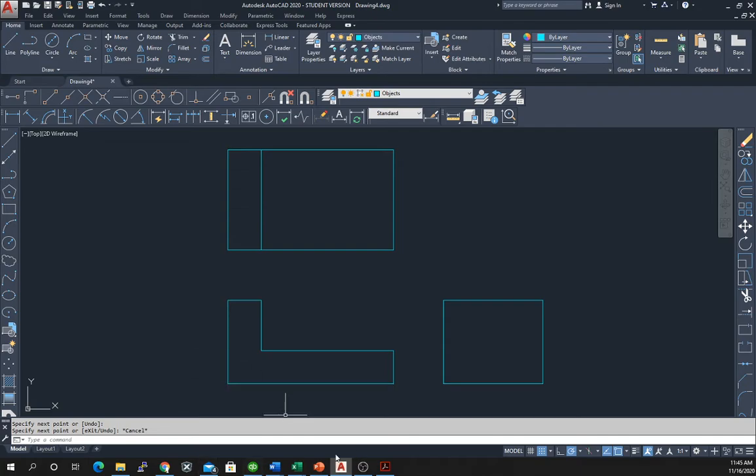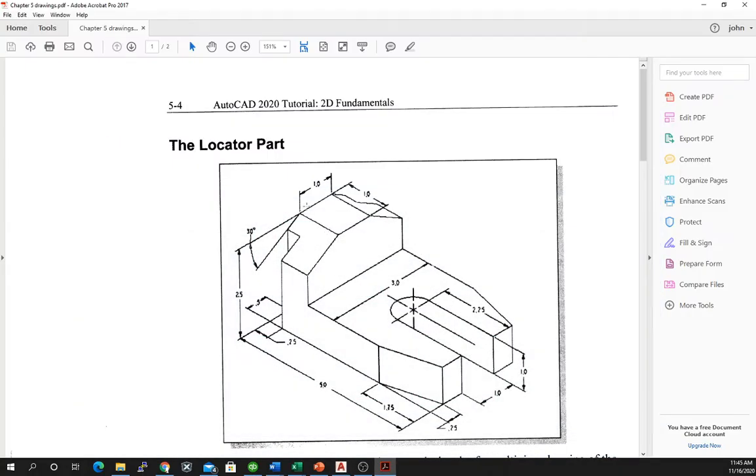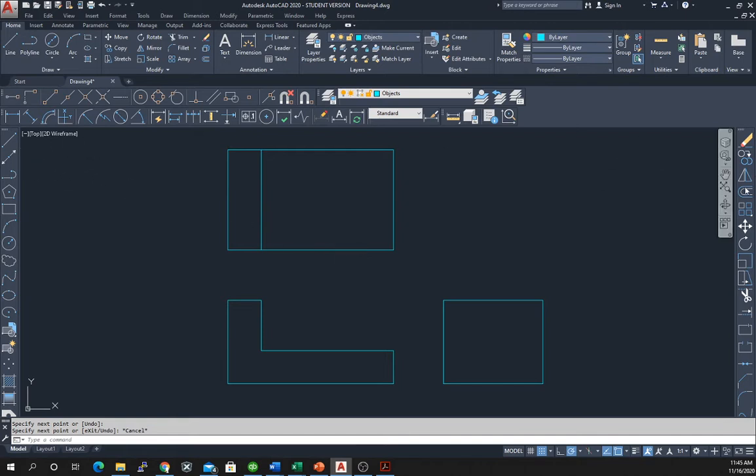Okay, so also now looking from above, you see that this is a 3-inch part, and then we have this cutout 1 inch in. So that means this is basically, I guess you'd call it trisected, right? Because we have a line at 1 inch, another line at 2 inches, and then it ends at 3 inches. And that actually goes all the way to the end here, because we have this separate feature up here that's also 1 inch. So what we can do is come back to our drawing and do an offset again.